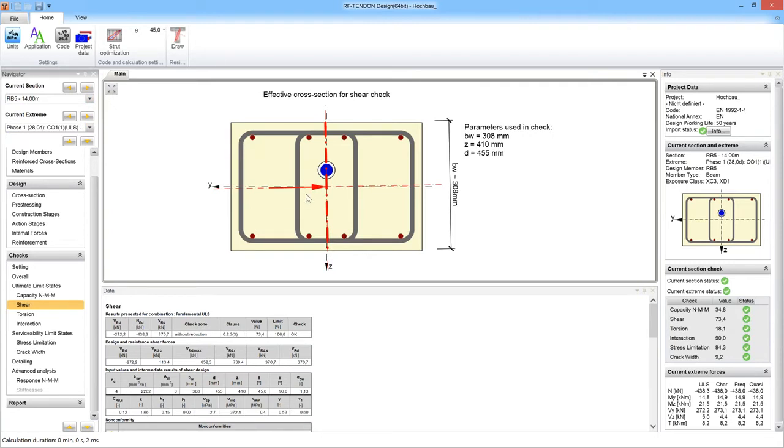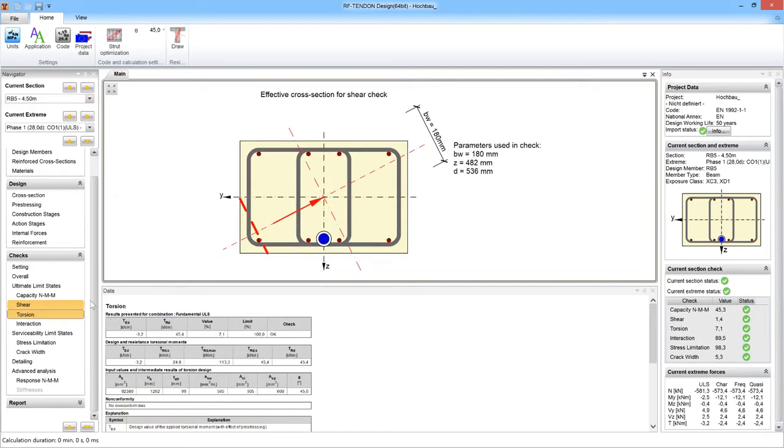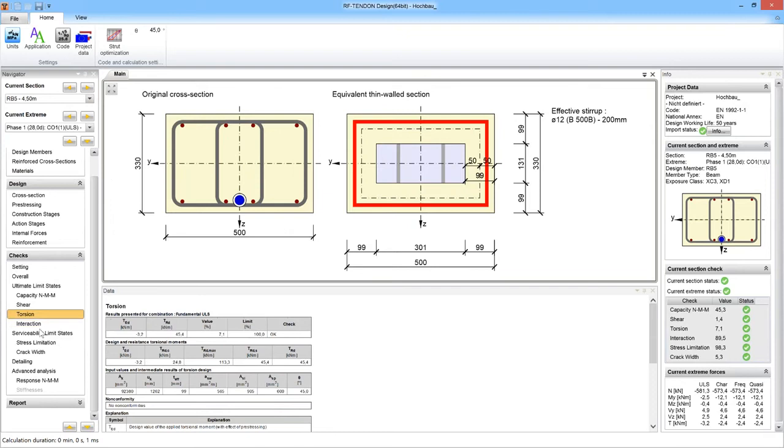If we apply a high normal force of pre-stressing, then of course just behind the anchor, we should not use the sectional analysis. This is the anchorage zone, but I don't think I made it immediately after the anchor, and still RFEM integrates quite significant forces, but we can design them with no problem. So let's go back to the midspan. Maybe I should have shown this torsion above the support, but it doesn't matter.